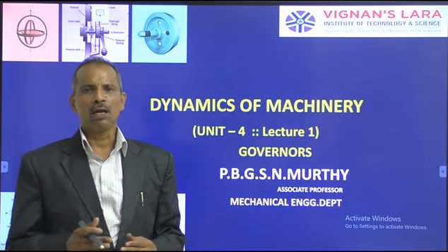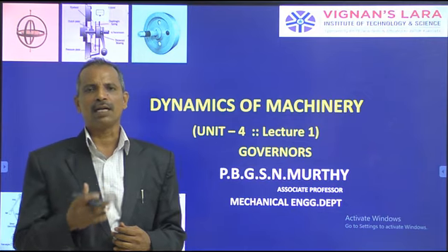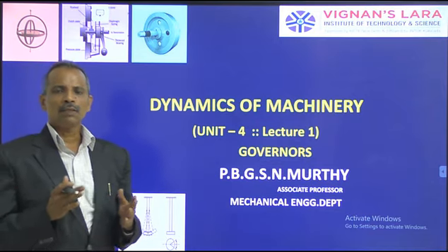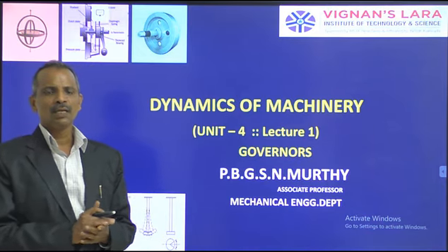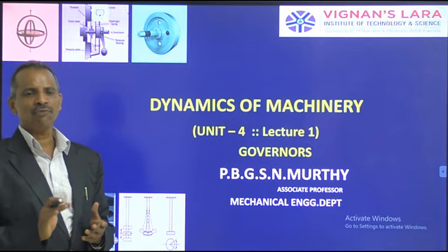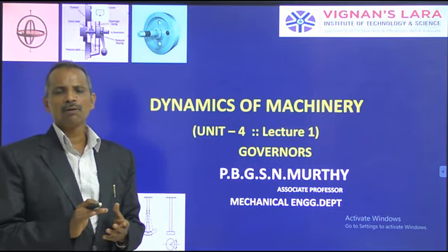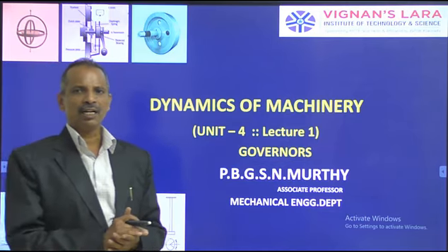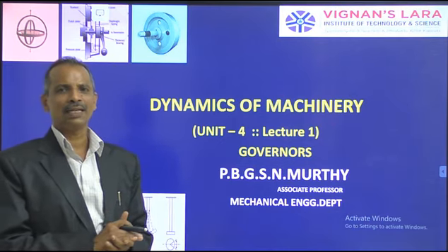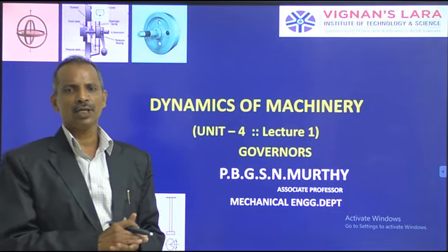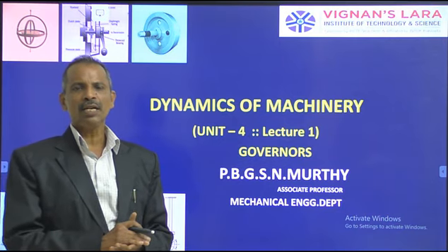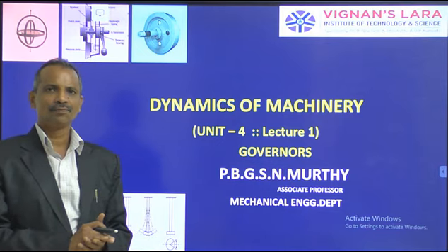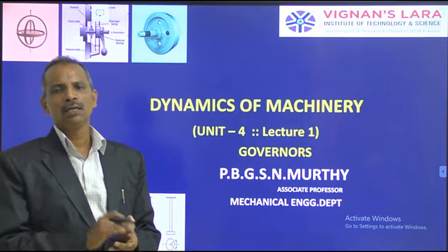When we start, okay. Now let us recall the flywheel, which we already covered, and what is its function and how a governor differs from a flywheel. We have seen a flywheel requirement is like this. If an operation or a process in a particular engine will have a cyclic fluctuation, then we need a device called flywheel. Cyclic fluctuation means, irrespective of the external load that comes on the engine, there is a variation in the torque output, or the torque receiving, or whatever it may be. So the torque variation takes place every cycle. So in those cases we require a device called flywheel.